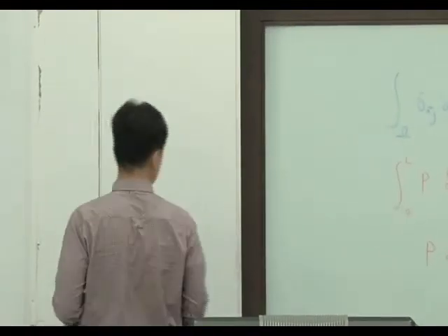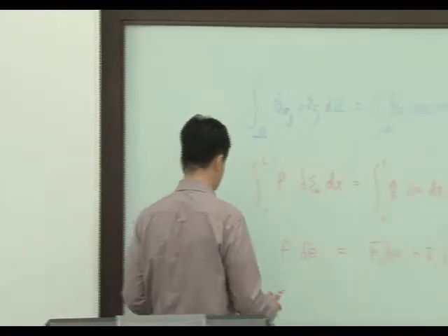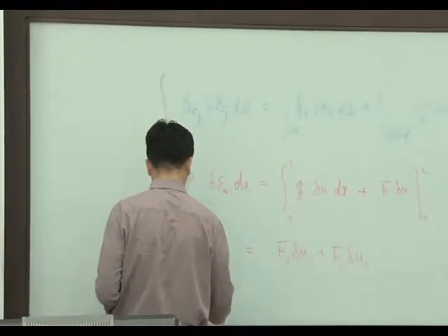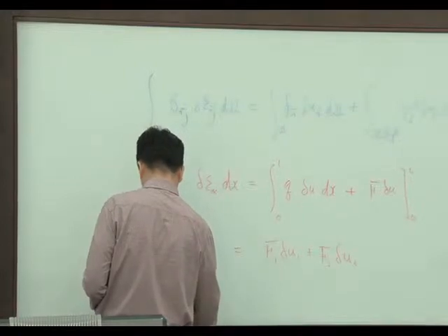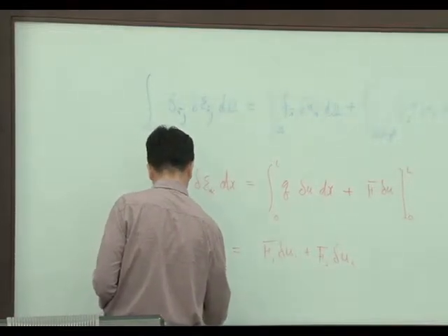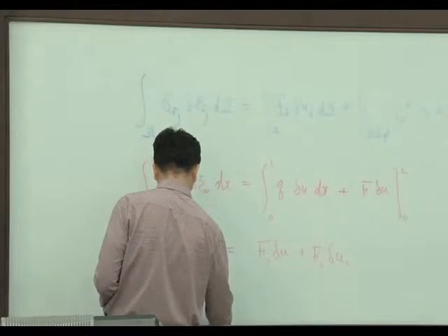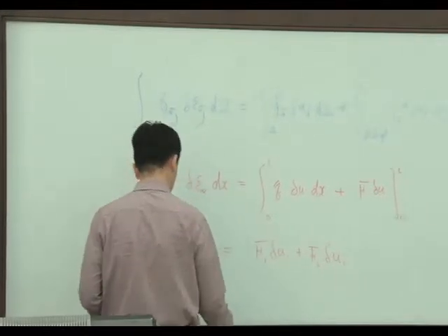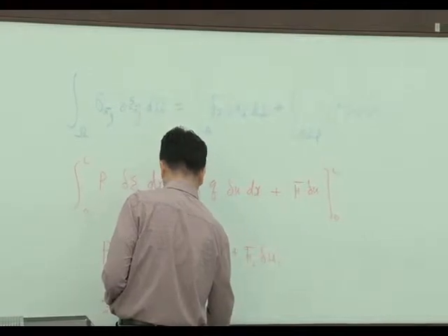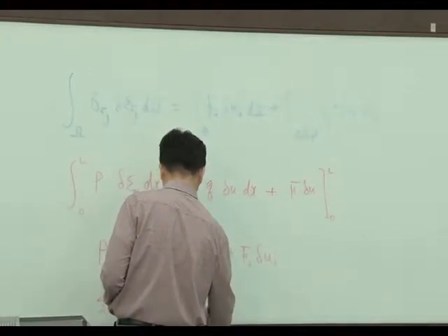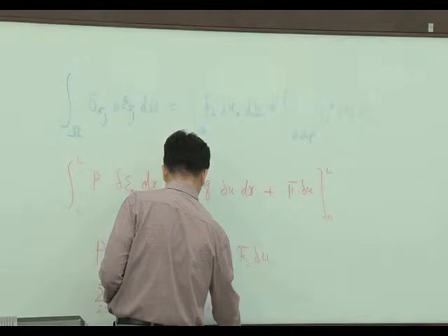And for a general truss system, which has many members, this equation can be modified like this: the sum over i equals 1 to N of P_i delta_i equals the sum over i equals 1 to M of F_i U_i.